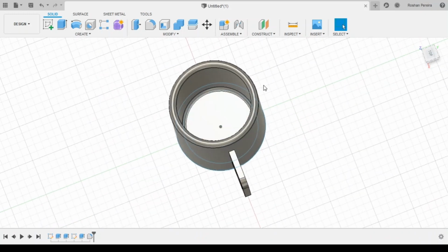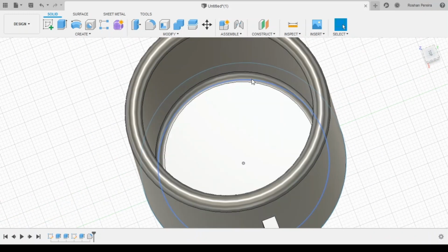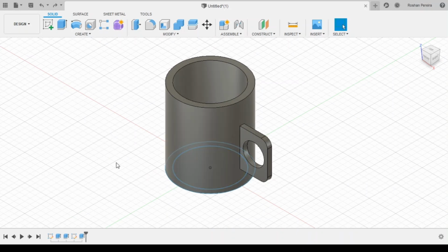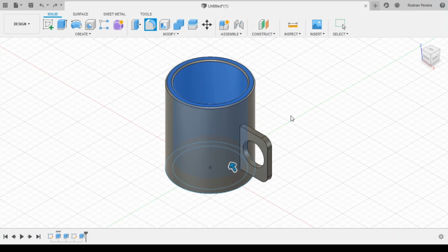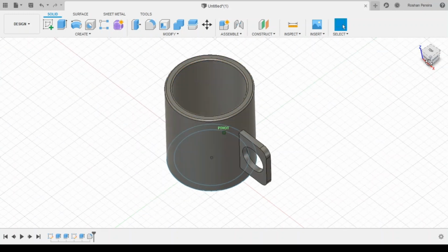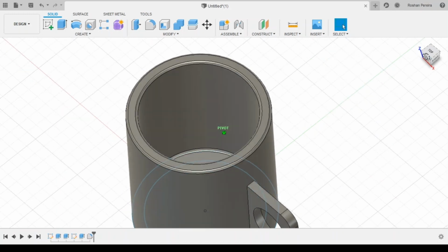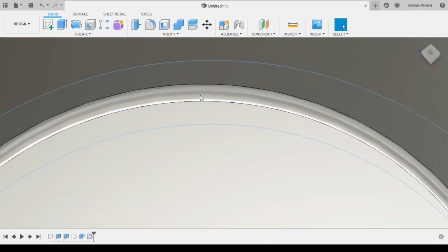There's also one more fillet that is on the inside. Since our fillet changed the interior dimensions and removed the interior circle, we'll go back and change it to a lesser radius. We'll do that fillet thing again. Fillet, the top and the interior. And I'll make it 1 instead of 2.5, because 2.5 is, I think, the limit. So if I make it 1 and I say OK, there are nice edges here which are not sharp. And there's a fillet on the inside also, if you notice here.